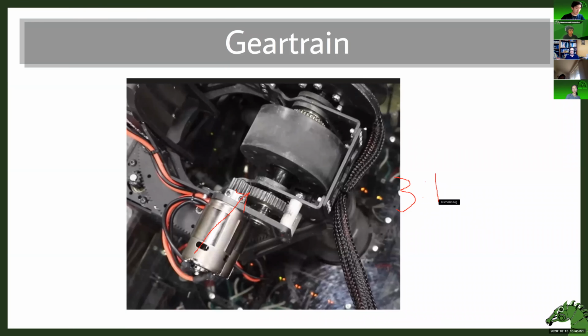Now, if you think about the final ratio, for the purposes of shooters, a lot of the time you're looking at surface feet, which is basically as a wheel spins, how fast is the surface of this wheel moving? So you calculate that by finding the circumference, and you do some stuff with RPM. But basically, if you have a loop of paper and you were to cut it and lay it flat, that's like one rotation, that's the circumference. And you use that to calculate things like surface feet.